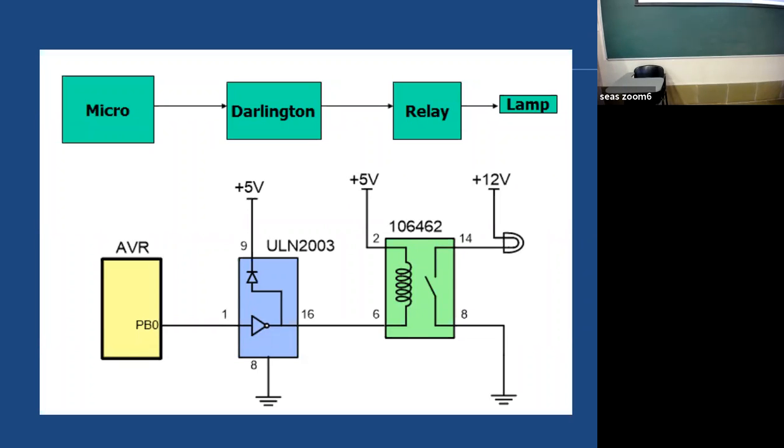Now here is one circuit where we have a microcontroller, we can amplify current, we have a relay, and we have a lamp. The lamp is working on 12 volts. Here it is, this is the switch. Now you can activate this switch based upon the current in this coil. Plus 5 volts here, you should send logic 0 here so that the circuit completes. Magnetic field is there, it closes or opens this switch. So basically you are controlling this through the port pin.